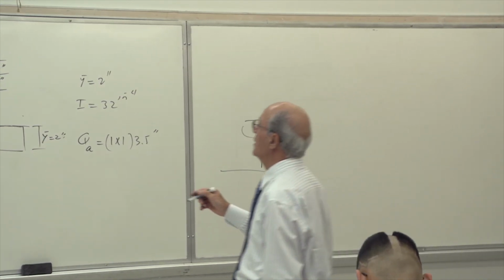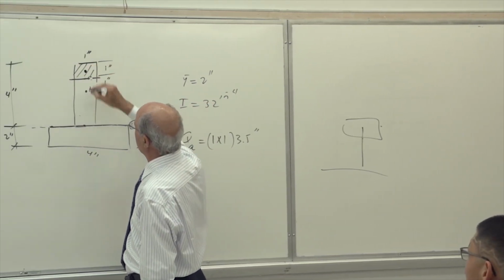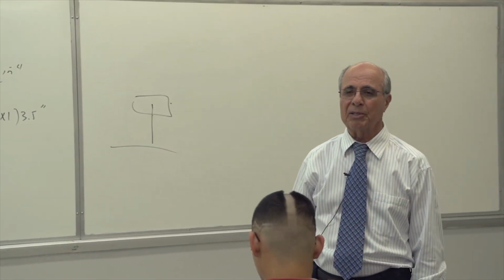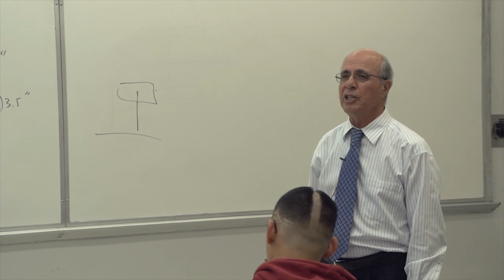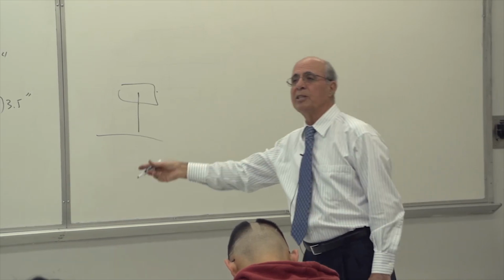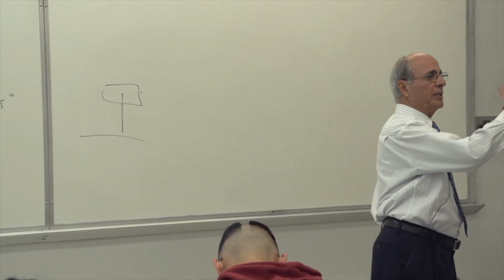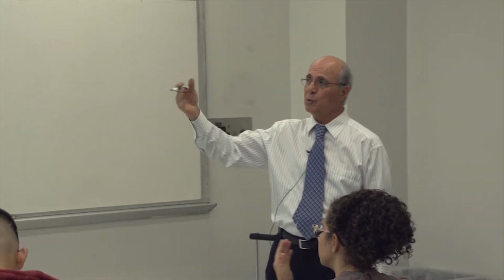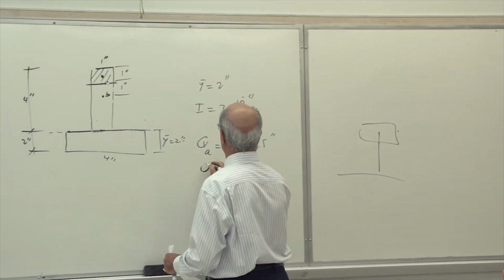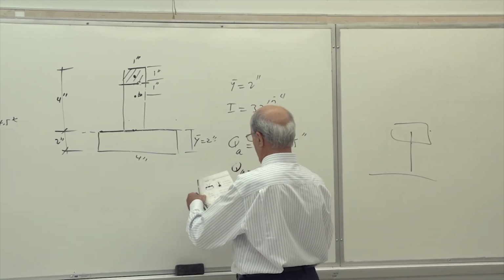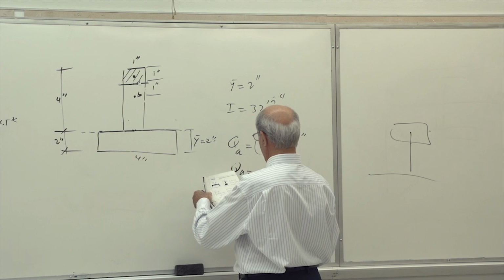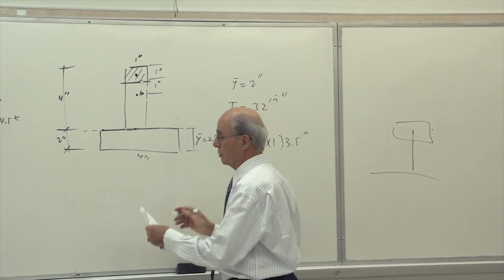So it's 1 times 1. You put the mass here as if it is a mass, and you take the moment about the neutral axis, which is the distance of 3.5. Yes or no? So what's the unit? The unit is inch to the power of 3. Remember, we started with the area, then the Q, and then moment of inertia. Inch squared, inch cubed, then inch to the power of 4. I showed you that system many times in the past. Is that correct or not? Therefore, QA becomes equal to, write it down here. QA becomes equal to, how much was it? I had it somewhere else.